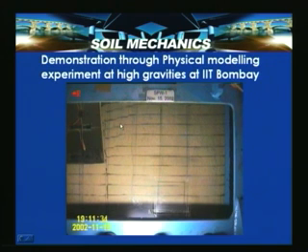As the wall moves away from the fill, you can see that the soil followed the wall and settled in this case and induced the rupture planes. Because of the condition represented here, this particular state is a plastic equilibrium state. The rest is still in elastic equilibrium. These are high gravity experiments carried out at IIT Bombay using the National Geotechnical Centrifuge facility available at IIT. In this case the soil has not yet reached the passive state, so the sand marker lines remain intact.